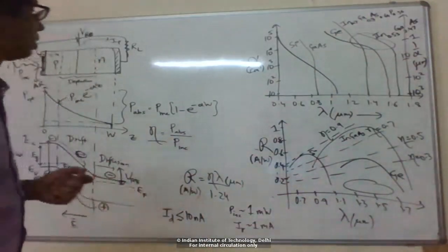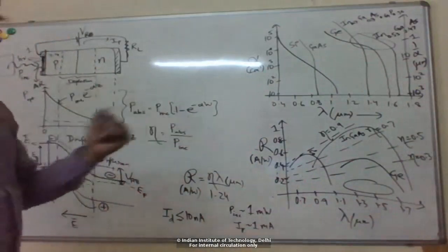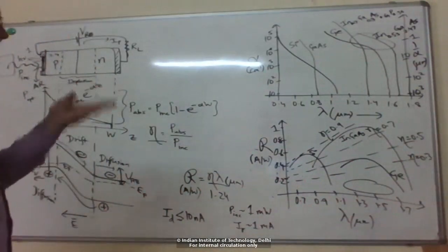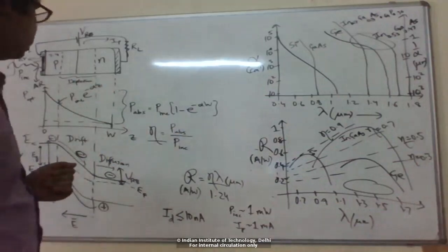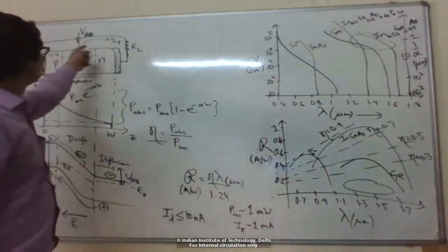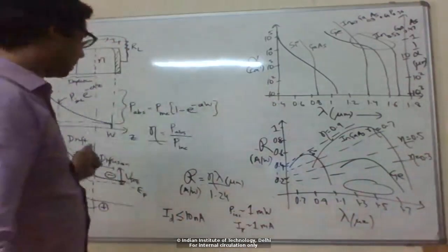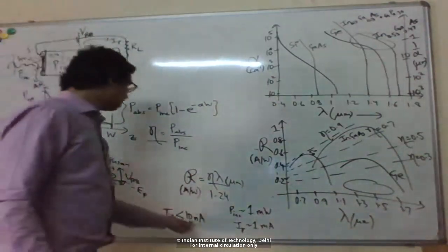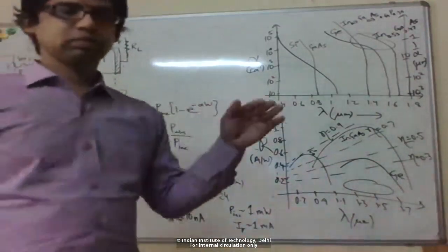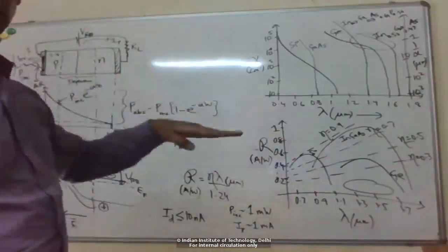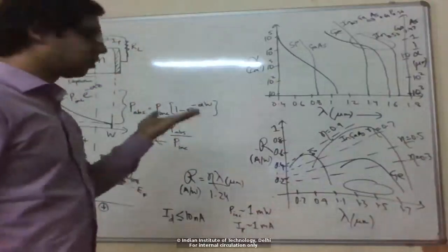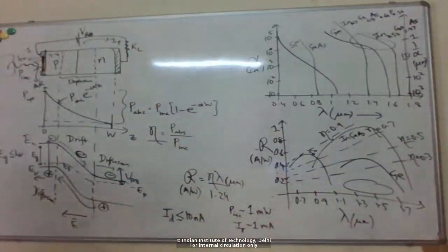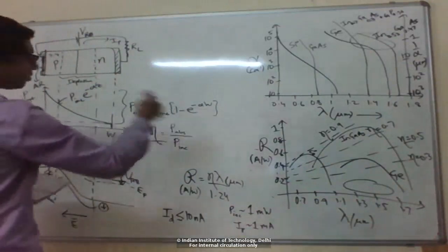But it might matter, for example, if you're doing on-off keying, right? For bit 0, let's say you're not sending any power, right? So ideally, your photocurrent should also be 0, but it will be non-zero. There will also be other sources of noise you can see, but this can, especially if the level 1 has been attenuated to a very small level, then it can give you some bit errors. Okay, so that's about the efficiency of the detector.